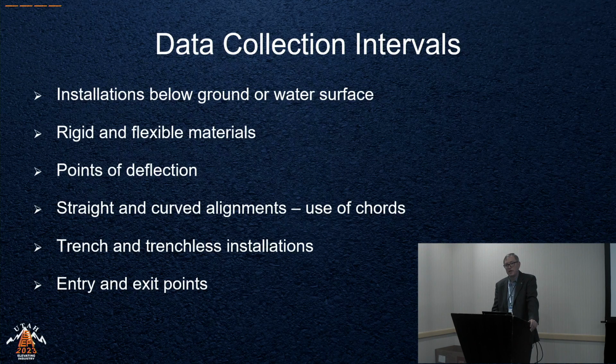While the standard was designed for utilities in every installation situation, there is a strong focus on things that are buried or submerged. The maximum interval between survey points on linear features is directly related to the desired accuracy. Anyway, what I want to say is if you want more accuracy, you have to take more points. Your intervals have to be shorter.